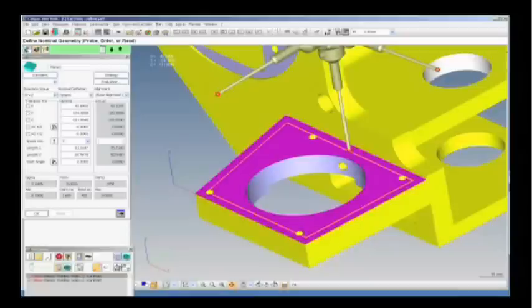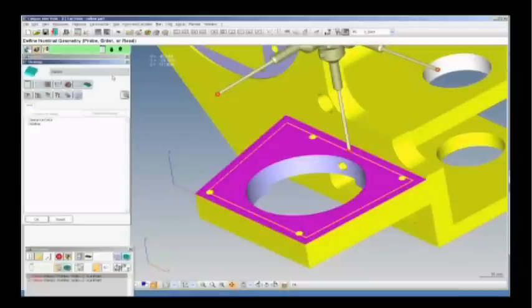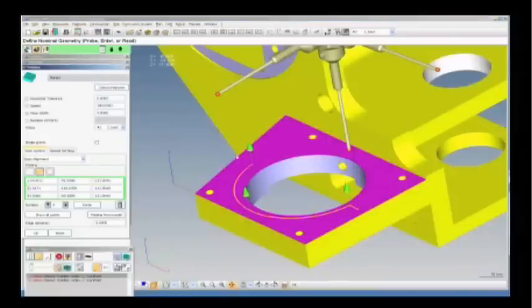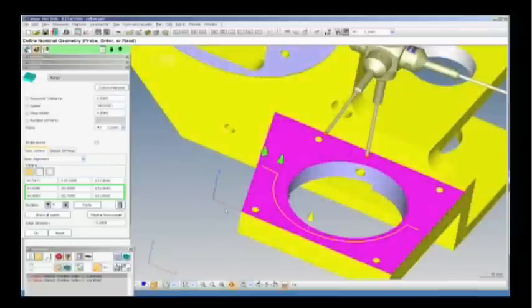Sure. So I can just tell it, use the back probe. I'll go into the strategy of this plane. I'll delete that existing polyline that was created. And I can just go in and create my own. And I'll say, I want you to go from here to here, here to here. Do that with an arcing motion. Kind of exit there.